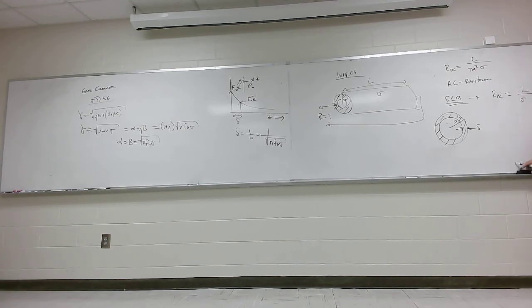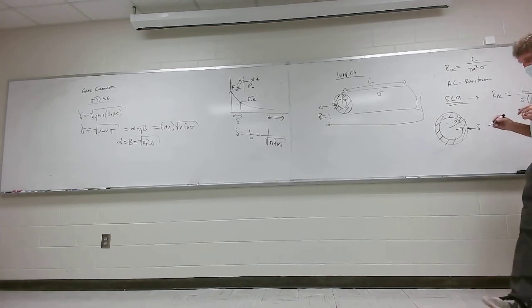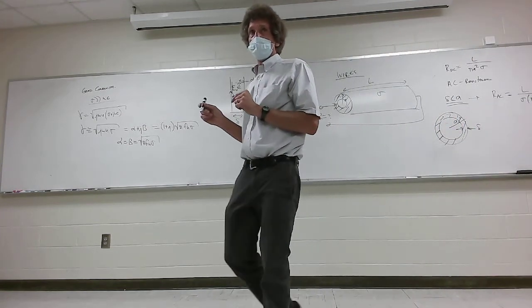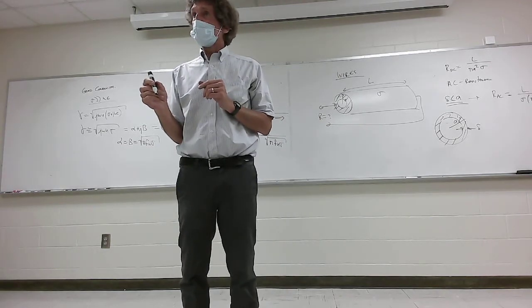But now, where is the area the actual current's flowing? It's a greatly reduced area, isn't it? That area would be the total area. It would be pi a squared, right? That'd be the whole thing, but then I have to subtract off that inner area. Let me say that again. I take the entire area, pi a squared, then I gotta subtract off that inner area. What remains would be the area the current flows through. Well, that inner area would be minus pi, not A, or not skin depth, it would be A minus the skin depth, squared. Take a look at that and see if you agree. I'm gonna simplify it in a second. Y'all agree with that? Sure, right?